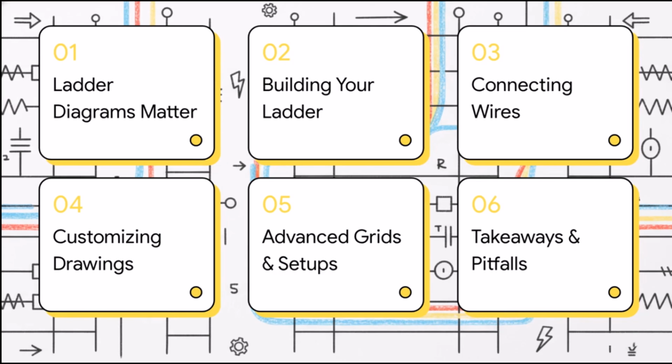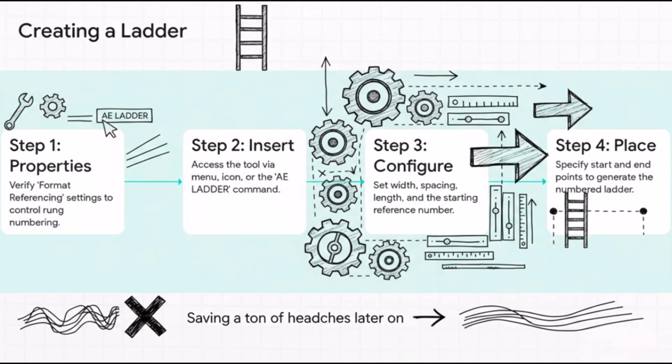Precisely. The energy is waiting. And then the horizontal lines, the rungs, those are the paths where that energy bridges across from hot to neutral or positive to negative. And that is where you place your workhorses. Exactly. That's where you put your relay coils, your pilot lights, your solenoid valves. Because they are arranged like steps on a ladder, every single rung receives the full voltage from the bus rails. It's a clean, perfectly parallel distribution of power.